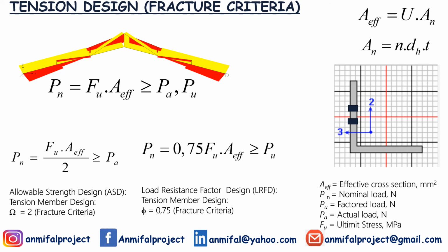For the fracture design criteria that considers the bolt hole presence, we should calculate the effective area first. The effective area can be determined by multiplying the shear lag factor U by the net area.